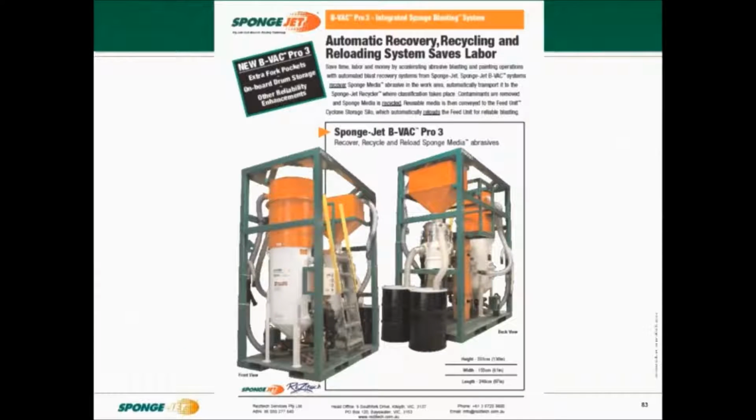That's 90% less airborne lead. The question is, will we need the same amount of air volume dust extraction as a garnet system? If we're using a BVAC unit, it has a significant benefit over garnet blasting. A garnet blasting environment, as it returns the media back to the system cyclonically, removes a greater amount of aspirated coatings and dust and the lead and puts it into the waste.